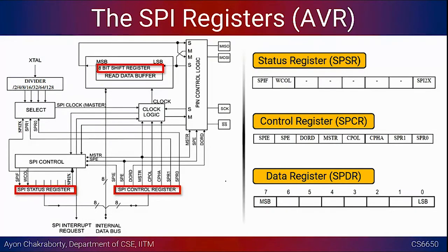And to do the entire control of this scheme and implement the different features inside the SPI subsystem, we have two registers: the control register, which has most of the functionalities, and the status register, where we mostly used the interrupt flag, the SPIF, and the speed doubler as a part of the prescaler, right? In the control register, the last 2 bits were used as the prescaler, along with this one, the data rate doubler.